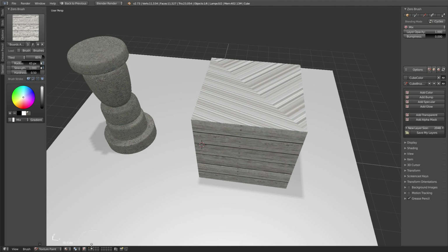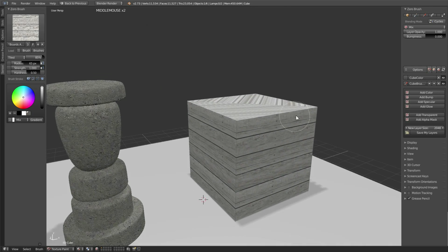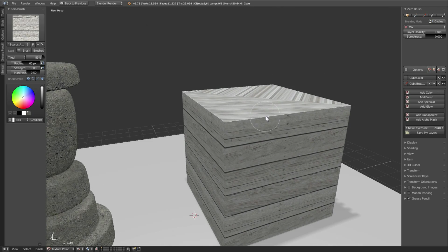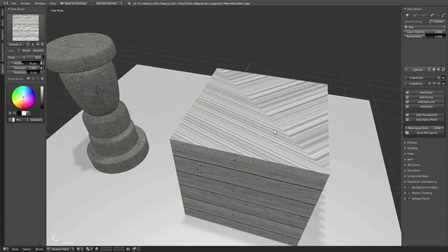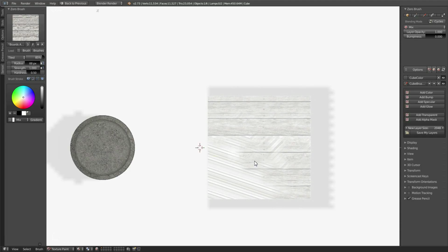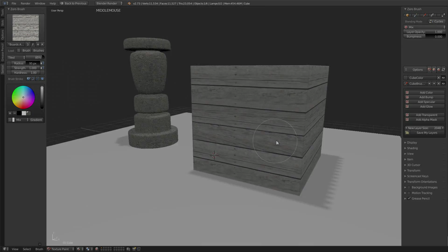But in this situation, I'm just going to click this little button here, which allows us, if we hold Alt and then click, to select faces. And then once we do that, our paint will only go onto that selected face. So that's helpful. So I'll press 5 to go to top view, and I'll just lay down a simple rest of this wood so it doesn't look so entirely bad. Increase my hardness so that this goes on really quickly. And there you go. So that's pretty cool.